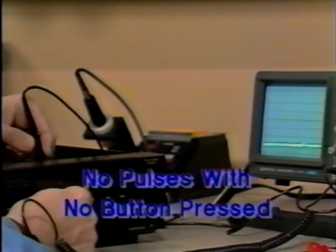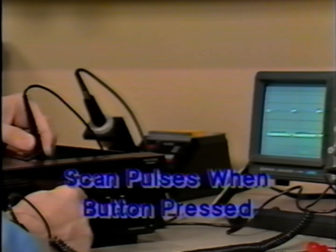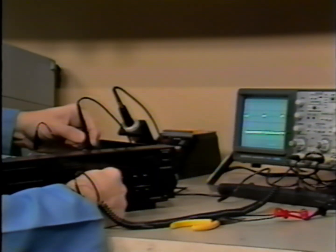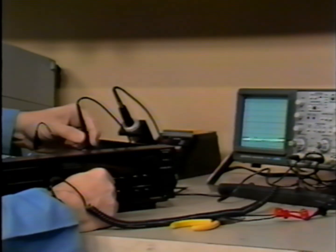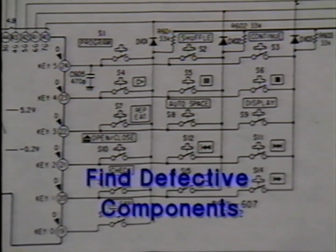When no push button is being pressed, the input line should remain inactive. When a button is pressed, the scan pulse should be present on the input line. By observing the output scan pulses and the input scan lines, it's easy to identify defective switches, resistors, and connecting cables.